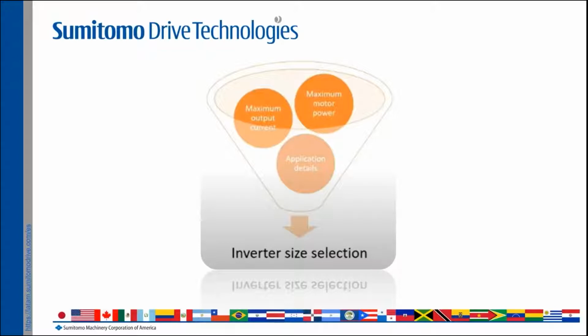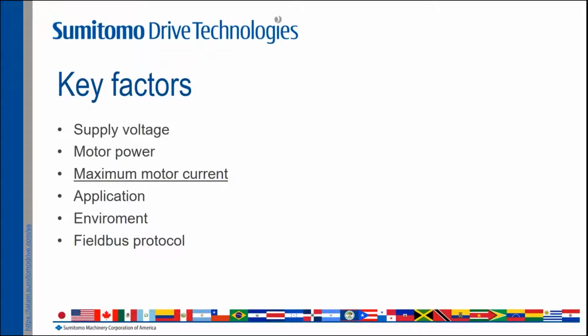The most important we consider are these factors, starting with the supply voltage available for your drive. Of course, the motor power that will be required for the drive, and also the maximum motor current.